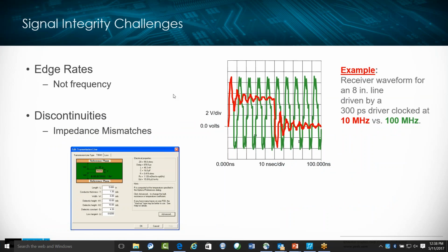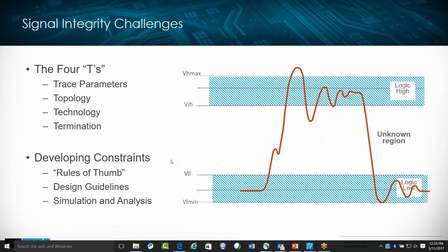So when we're talking about signal integrity analysis and what you get in the PADS Standard Plus, you do have the ability to view waveform shapes once you do a simulation of a trace. And you can determine the effects of your edge rates on that signal characteristics. Because we want to design impedance-controlled circuits to minimize the discontinuities and the distortion. All that capability exists in HyperLynx SI, and you get much of that in the PADS Standard Plus.